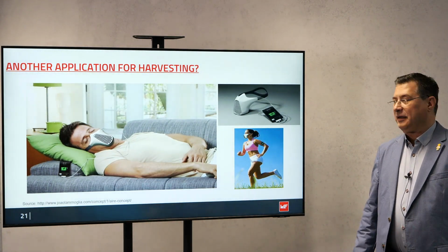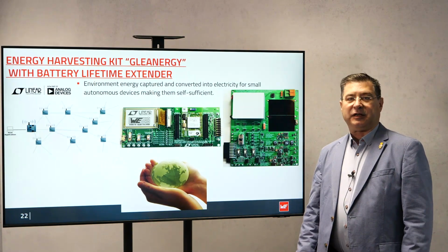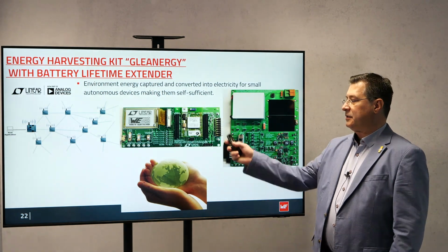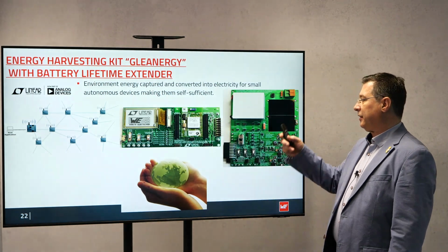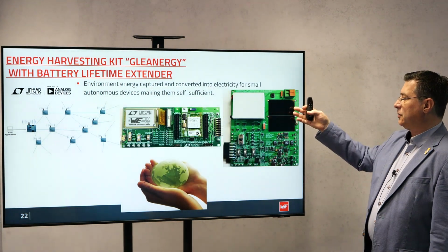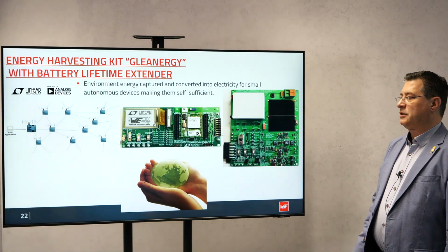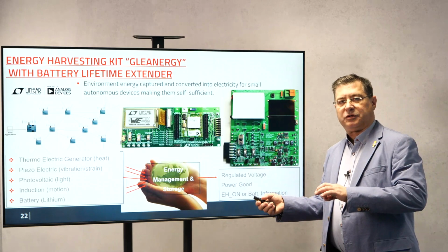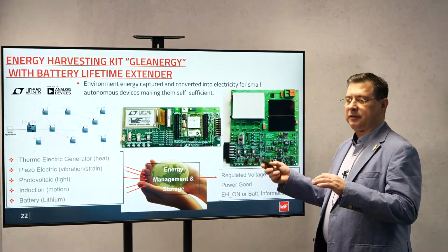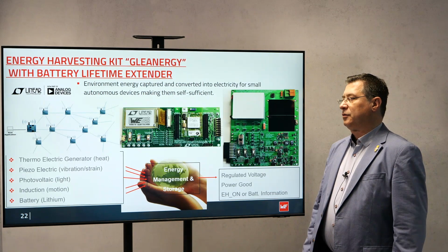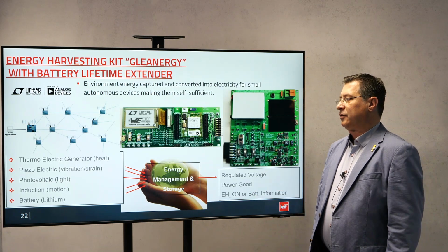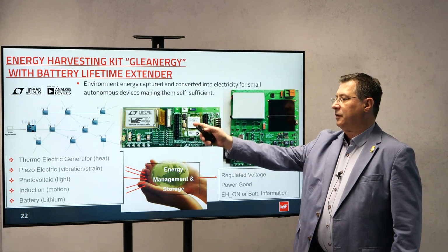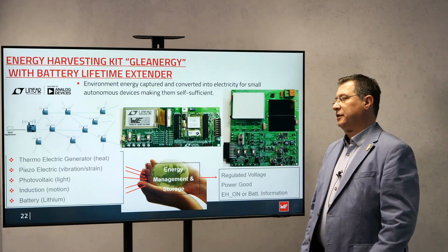And if you want to build anything like that, you can use the demo kit which we developed together with Analog Devices, formerly Linear Technology. There's a wireless mesh network chip already. You can have different harvesters like TEG, solar, or you can add different harvesters yourself. All the battery management is already on it. You can use different jumpers if you want to use a primary battery, a secondary battery, or a supercap or not. It's possible to detect everything, and you have a dongle you can connect to the laptop to get all this data, and also a shield PCB where you can put different sensors.